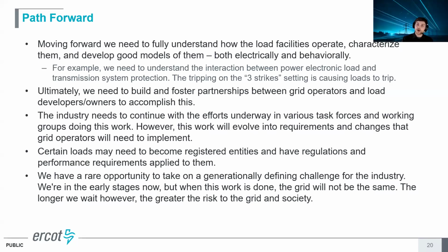So moving forward, we need to look at these loads and really understand how they operate, characterize them, and develop good models of them, both electrically and behaviorally. So in response to transient disturbances and steady state conditions, and then behaviorally, what do their load profiles look like? So we need to understand the interaction between the power transmission system protection and these power electronic loads. And so we really need to build more partnerships between grid operators and load owners and developers, which is underway in these various task forces. So the industry needs to keep doing that.